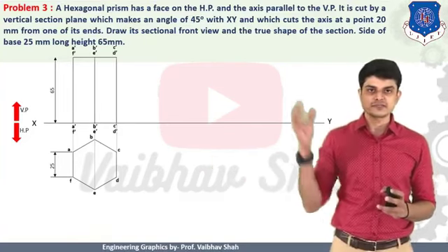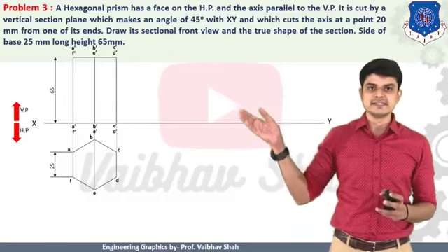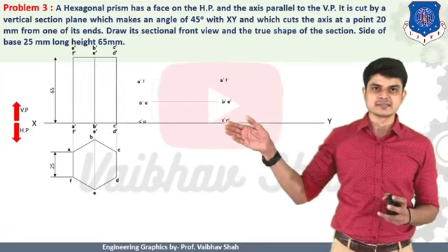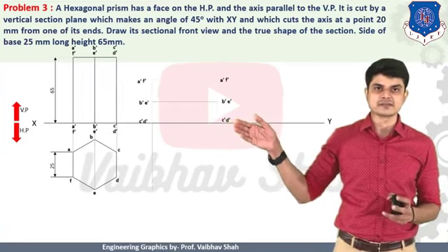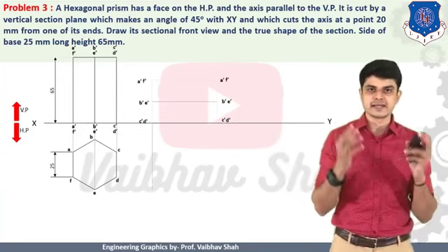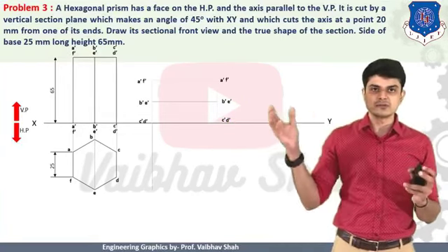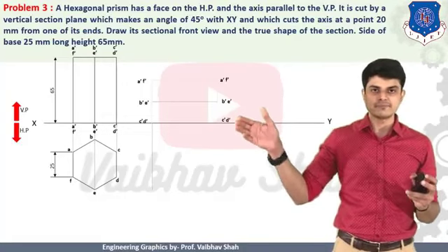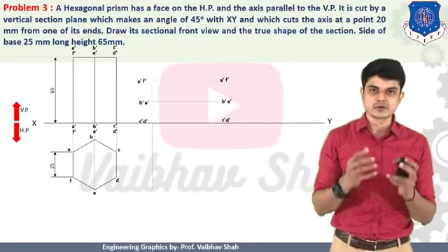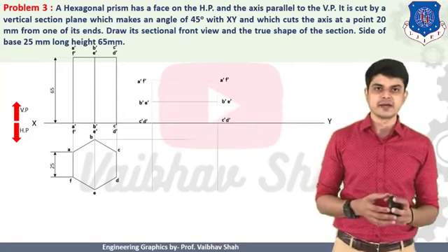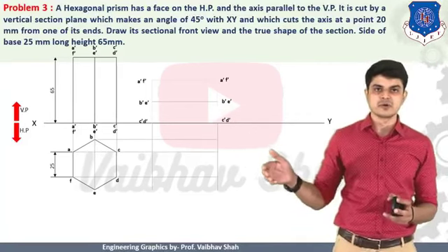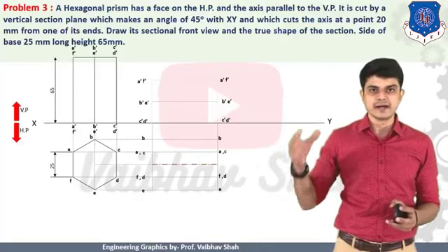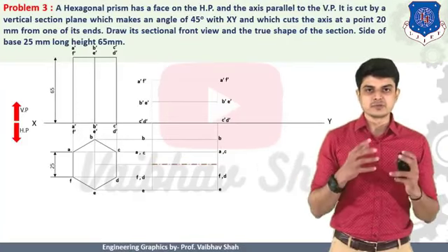So now let us put this vertical line of C dash C dash and E dash D dash onto this horizontal XY line. Let us put this object like this, and we will have our final object something like this. So this is your hexagonal prism front view drawn in the position in which your rectangular face is now on your XY line. After having this object, you should draw its top view. So let us draw a vertical line from each and every point, and horizontal lines from your previously drawn image, and you will have our final object generated, which is nothing but your required hexagonal prism top view.